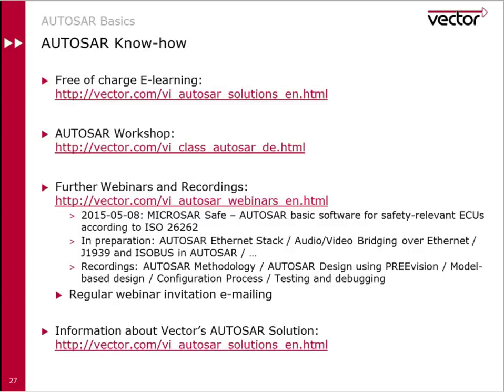Also very often is the question about how to handle the safety applications. For sure, AUTOSAR is designed to support safety. Different measures can be used for that. Memory partitioning for sure is the first, most important to guarantee the freedom of interference. E2E communication to communicate through black channels like a CAN network or something else is also supported.